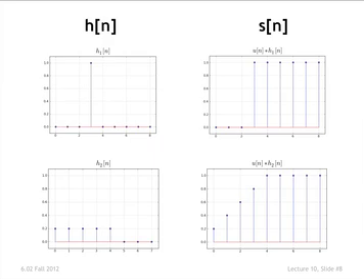You can get more elaborate sorts of unit sample responses. Here's one that changes sign. And correspondingly, what you find with the step response is that it's not a monotonic increase to the final steady state. There's actually some oscillation before it settles down. Okay, but it's the same idea. You're computing the area under this, if you like, but the area goes positive and then slightly negative and so on. Well, positive and then less positive. And so that's what you're seeing up there.